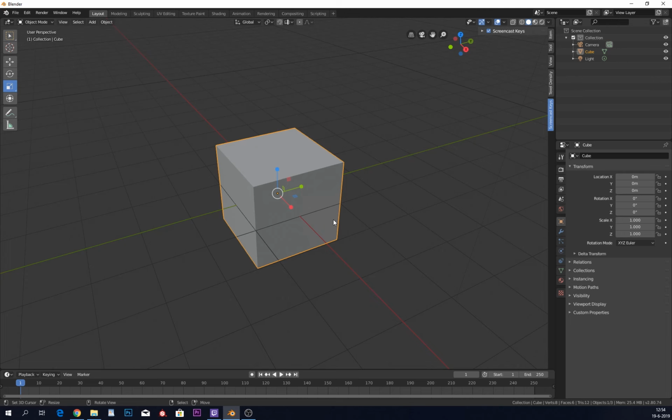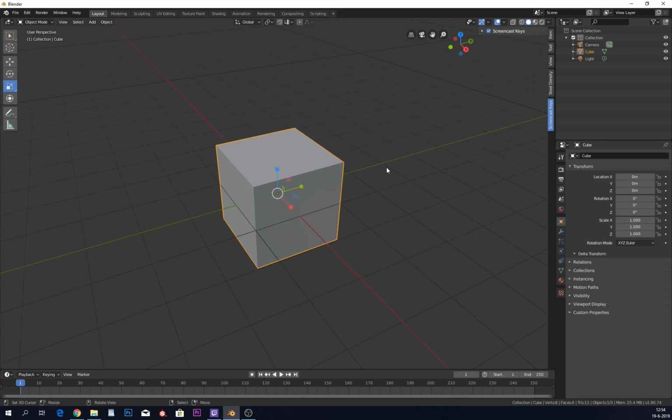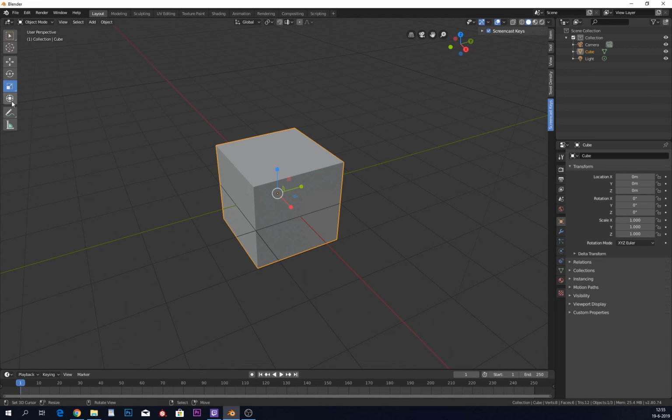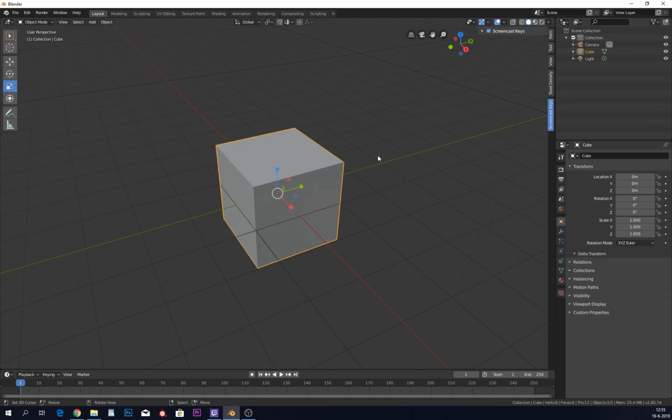So for scaling, also very easy shortcuts, your hotkey, whatever it's called, S. S is for scaling. And here as well, you can choose whichever axis, scale around the Z axis. Or if you don't want to scale around anything, scale Shift Z. If you don't want to scale around the Z axis, I mean. And those are multiple ways to manipulate our geometry.